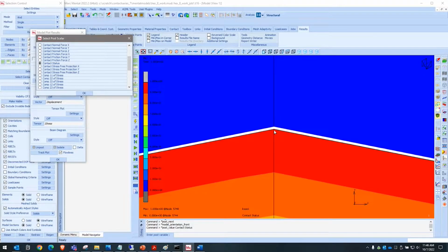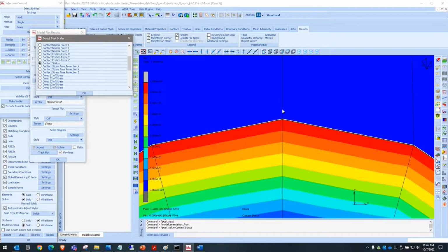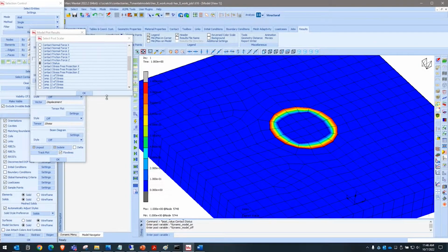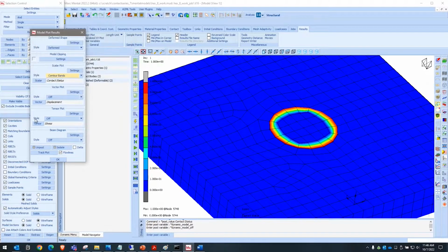And the reason for that is we're saying this node makes contact 20 microns before the other face. In other words, one way of looking at this would be we're forcing some kind of a 20 micron shim in between these two, but we're not modeling it, or we don't see it. So in terms of the effort to set this up, this is a lot less effort than anything else.